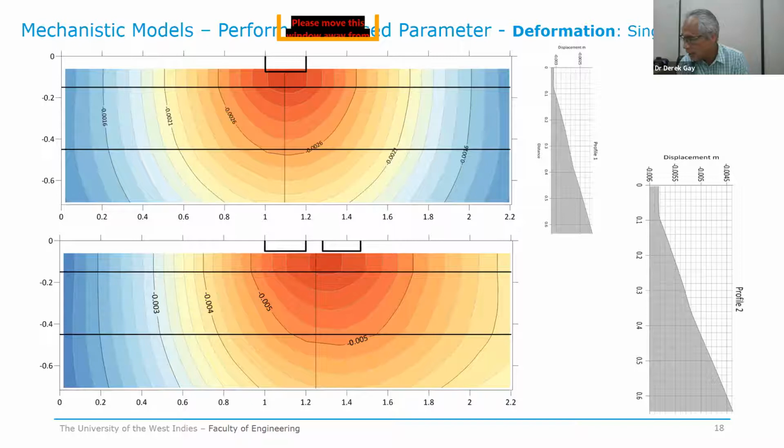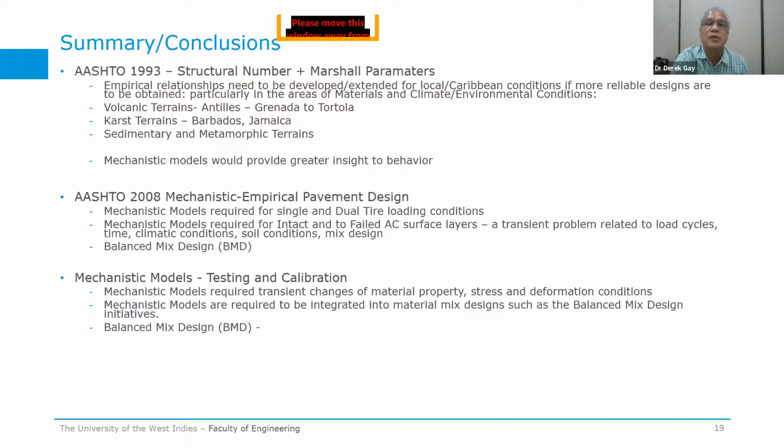And the sub-base stiffness, from my little notes here, is about 4 times softer. And it's about 10 times softer as you go from sub-base to subgrade. So when we switch to deformation, a performance-based parameter, we find that we have to look more at the lower layers, because those are the ones that control what you see manifest at the top as the asphalt ages. So I'll stop here. I just have some quick notes, really, not any hard and fast conclusions.